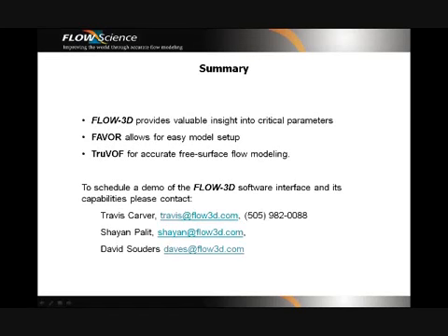First, in summary, as can be seen in this presentation, Flow3D can provide valuable insight into critical parameters of a wide range of design problems in hydraulics engineering. CFD is a beneficial tool for quickly testing designs and finding potential problems, and this presentation demonstrated how customers were able to improve a deteriorating fish passage and determine if a revised probable maximum flood condition would adversely affect a spillway. We also covered a couple of our core strengths, primarily how quickly a model can be set up because we make meshing simple with our FAVOR method, and that Flow3D can accurately simulate free surfaces, and that is key in many hydraulics applications.